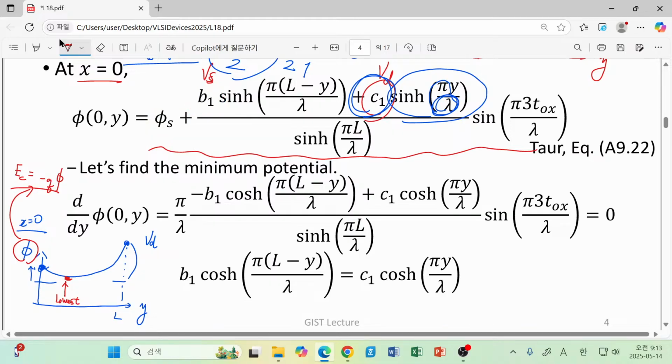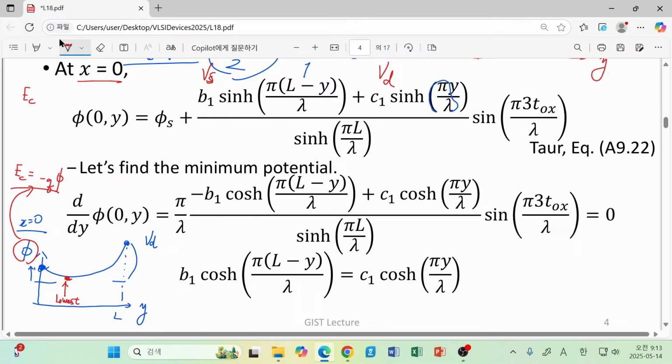If we wanted to be really rigorous about it, then the actual way we get this EC value should be like this: just multiply minus Q to our conventional electrostatic potential. And by taking this number, what is the physical meaning of minus Q times phi? That will represent the energetic position of our intrinsic Fermi level.